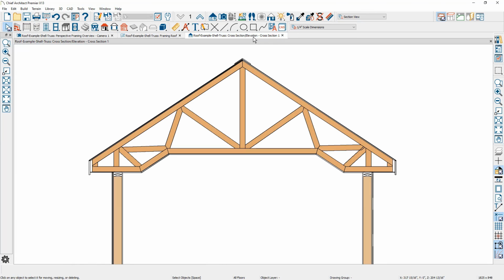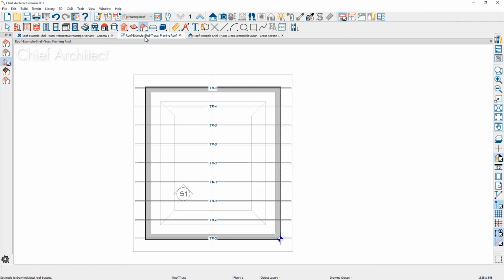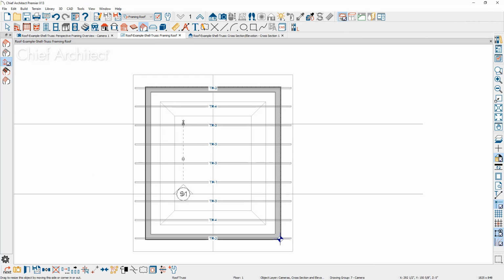The trusses will follow your ceilings whether you've created a tray or a vault. You will have to force them to be rebuilt if you draw them after the fact. All of these truss envelopes can be modified. If I click on this truss, notice that there is a polyline indicated by each one of these diamonds. You can actually come in here and modify this. If you pull it up, you can see that we've generated it. My section's cutting back through there. Let's just adjust it so we're looking at one of the trusses. Let's just pull that back, go back into that view.